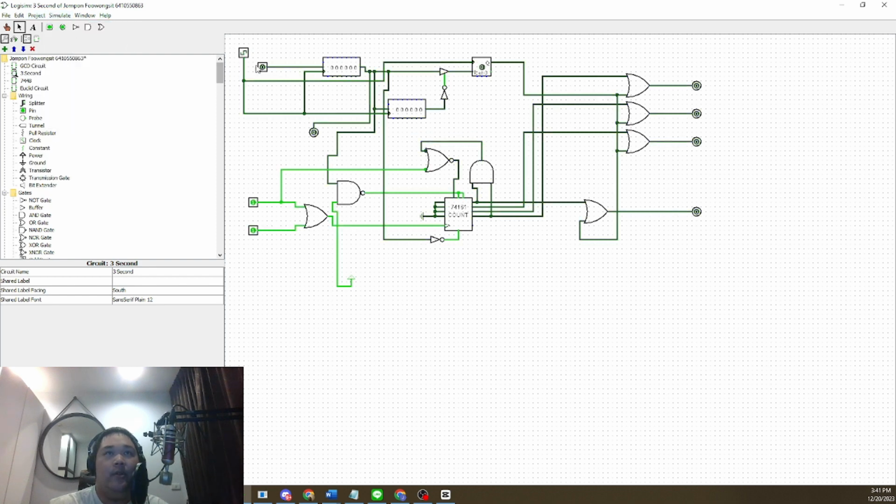Let me show you here. I put 1, so we start resetting with 1 in the shift register, and here it sends 1 0 1 0. So when 1 0 1 0 happens six times, when the 1 0 is sent out, it gets inverted to 1, so the T flip-flop sends out the signal 1 0 1 0 1 0, 3 times. That is how we made the 3 second circuit.